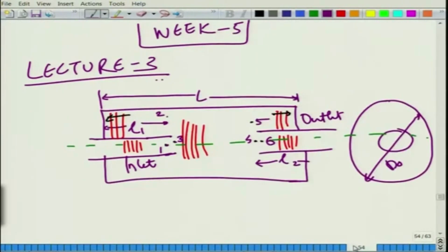Why is that? The acoustic pressure at this point is equal to the total planar wave pressure and is equal to the pressure of the section 2. This is one of the assumptions of plane wave theory, that the wave comes, it is expanding into a larger section, and over the entire cross section the pressure is equal. So, over this cross section, where I am pointing, everything is equal.